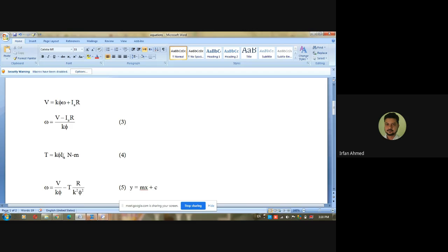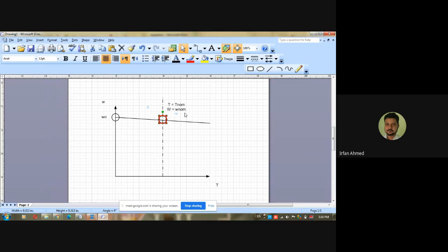So we'll see later how to find the value of C. If you have the value of C and the rated armature current of the motor, you can obtain the rated torque of the motor. The rated speed is obtained from the nameplate of the motor, and the rated torque can be obtained using the equation: rated torque is equal to C into the rated armature current. Okay, is this clear, everyone? Any questions here?